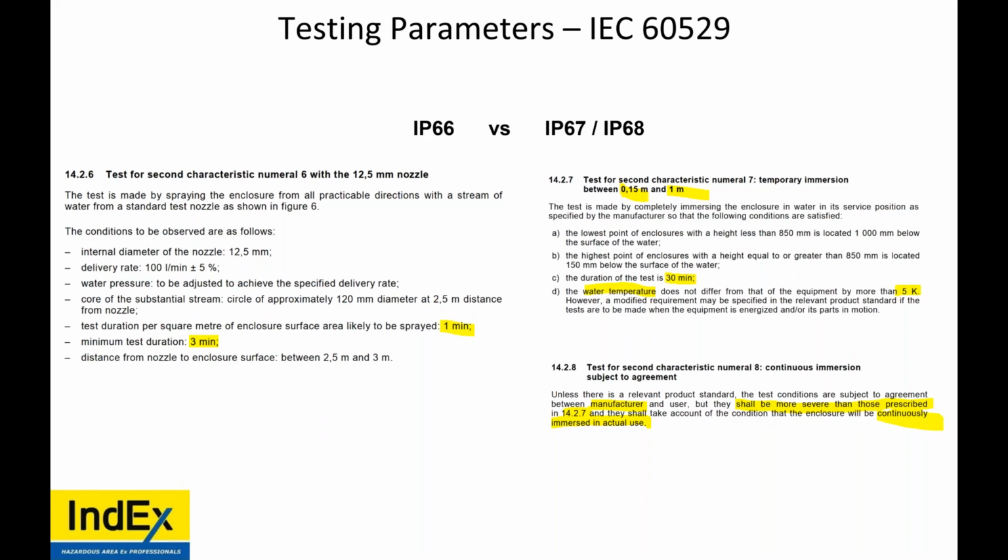When an enclosure is rated IP67 and has a cutout made for a cable entry or for indicator installation, how do you maintain the IP, and how does the requirement vary if installed indoors or outdoors? Well, when there's no threads, that can only be guaranteed to be IP54 with an IP washer. If there is no threading and it's just an open hole, you shall always use an IP washer.